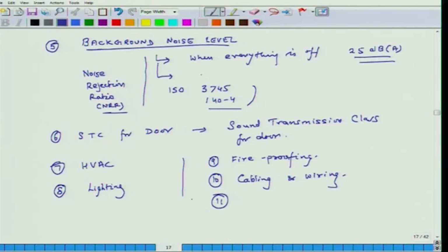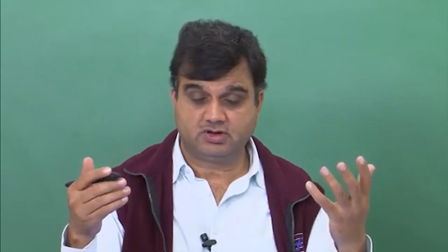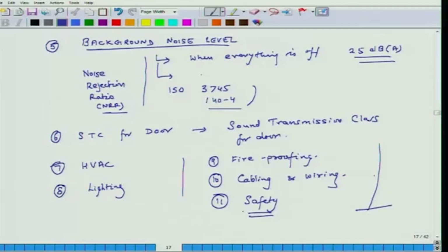And then an extremely important consideration which has to be provided in specifications is safety, because these rooms are virtually like sealed boxes. If something happens inside, it's very difficult for anyone outside to hear. So in case of an emergency, what kind of methods and protocols and fail-safe mechanisms are there? All these are important considerations for anechoic chambers.